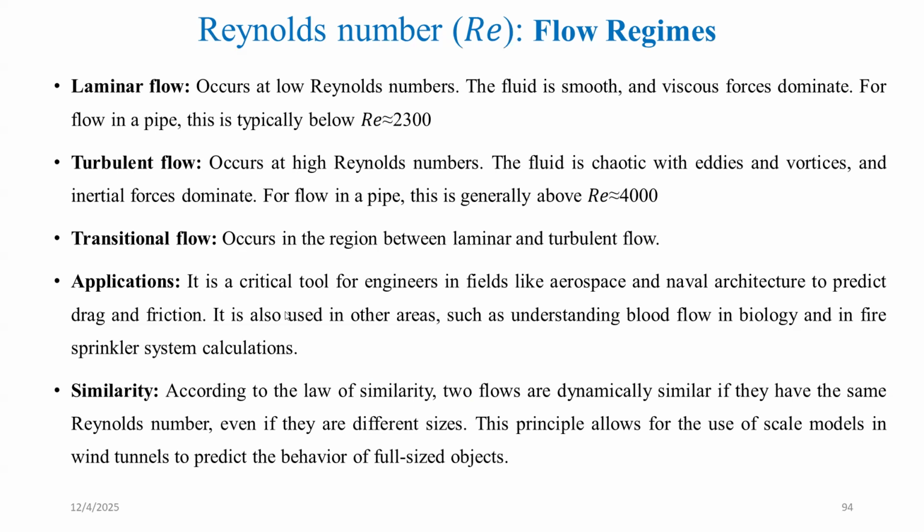Similarity approach is one of the important approaches here. According to the law of similarity, two flows are dynamically similar if they have the same Reynolds number, even if they are different in size. Some of the shapes or sizes may vary, but if the Reynolds number is the same, then we call them similar flows.